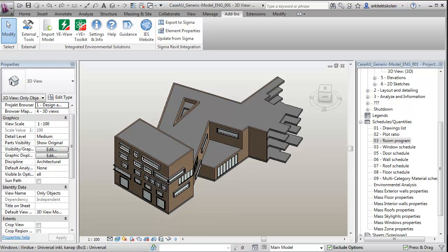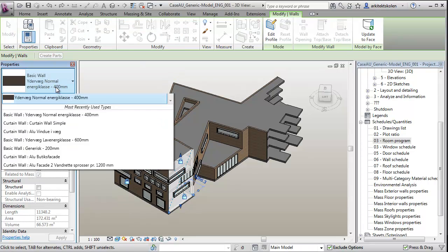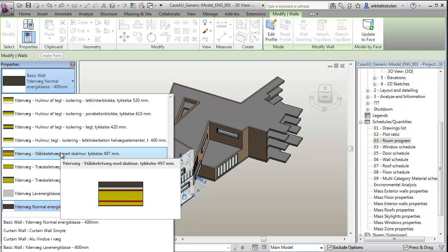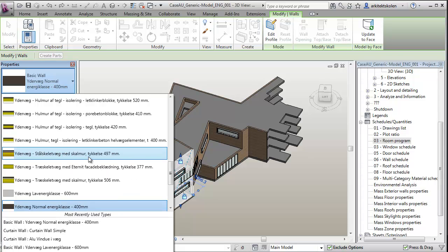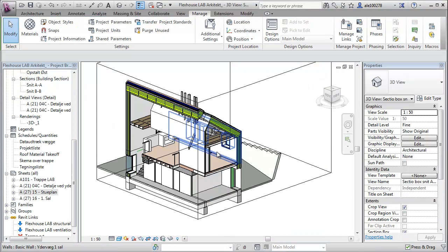Inside Revit, we can now go in and begin, based on the knowledge derived in the previous phase, to turn this very generic model into a more complex building information model with the right layers and constructions, materials, etc. And turn it into a model where we can now start to model things like MEP, construction models, etc. for doing coordination before doing the actual construction.